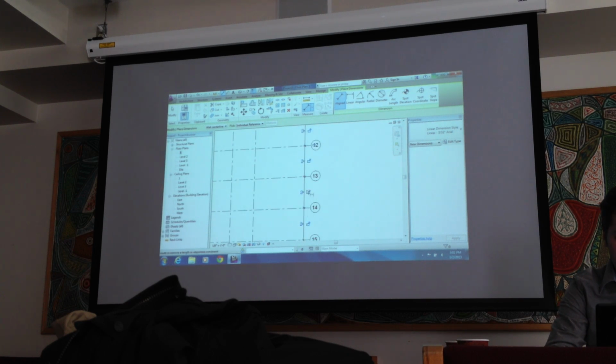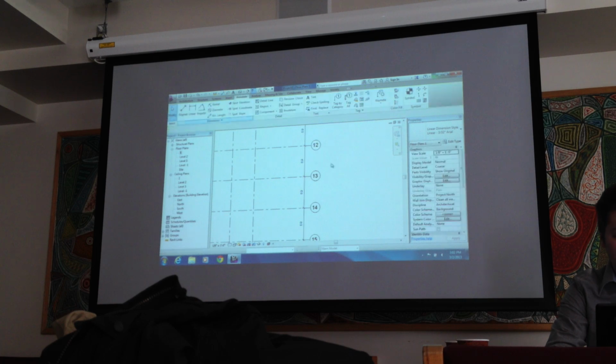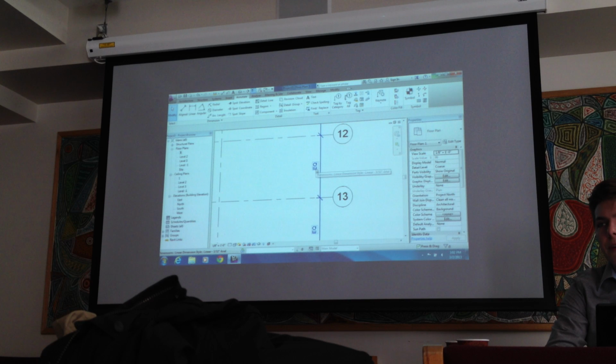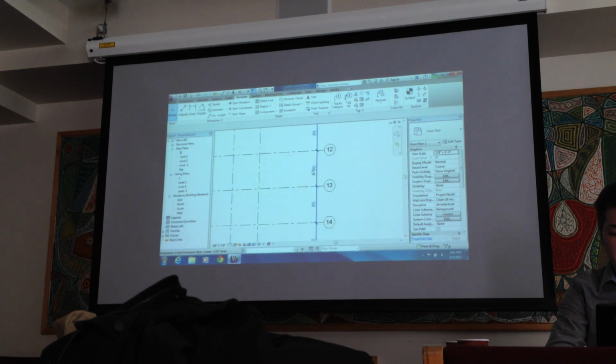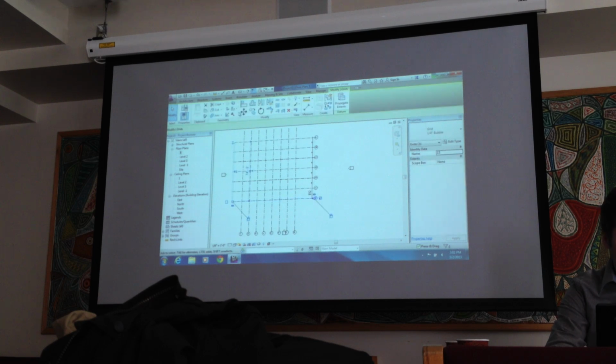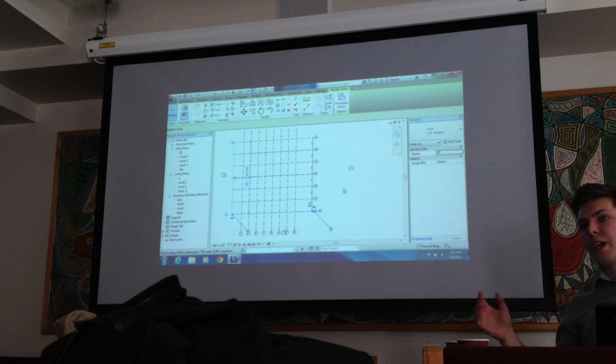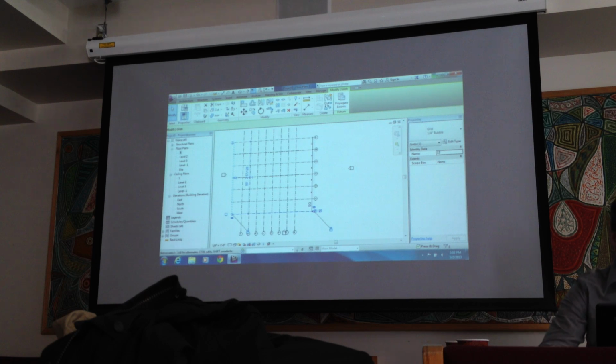And then you can lock them into place if you want, or you can delete it afterwards. See how it says EQ now for each one instead of showing a dimension unit? So now, when you move one, the whole thing will change, allowing all the grid lines to stay in the same dimension place, so they all naturally expand or contract instead.